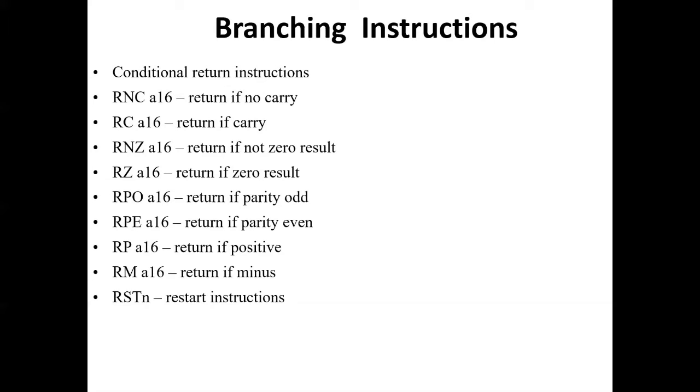Next is RC A16. RC is a mnemonic which stands for return if carry. This instruction is used to return to the main program only if carry flag value is 1. If carry flag value is 0, program flow continues in the subroutine sequentially.